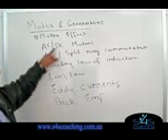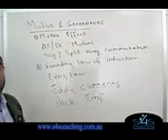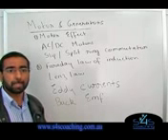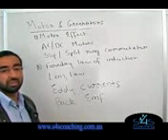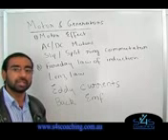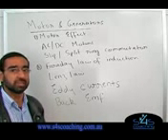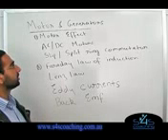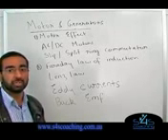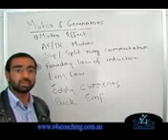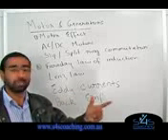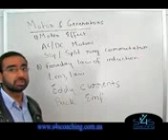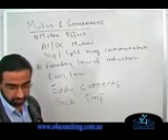So, looking at the first thing, the motor effect. The basic motor effect is the basic principle behind the running of any motor. Stated simply, what the motor effect says is that a current carrying conductor in a magnetic field is going to experience a force. Now, to find out which direction the force is in, you can use either Fleming's left-hand rule, that's for FBI, or we can use the right-hand rule. In this set of tutorials, we'll always be using the right-hand rule.